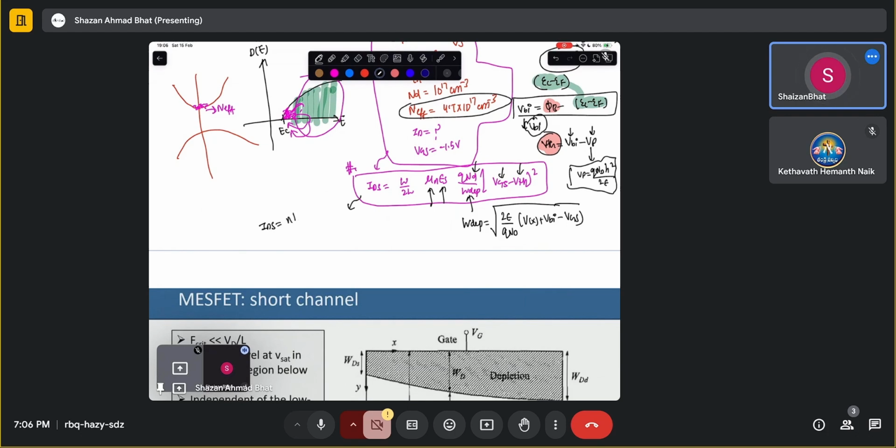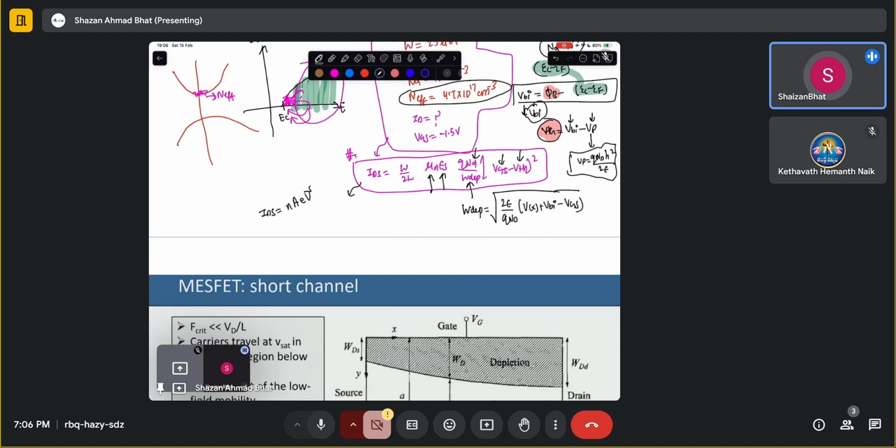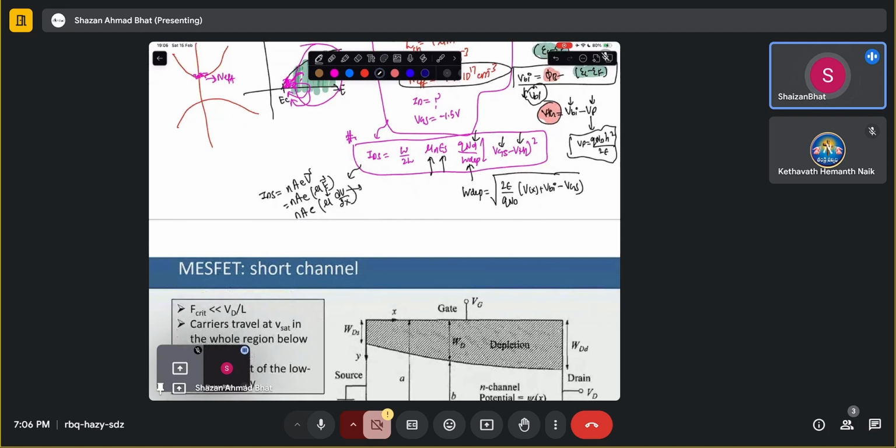It just comes from the fact that you know about this particular thing. If you know about the n q v_d thing, you can write it as mobility times electric field. You can just juggle with the things. Then you can write electric field as dV over dx, in terms of the voltage. Then you can replace it with the length. And then you have the area, you have the number, you can replace it with N_D. Then you have the mobility also. So these all come from these particular equations. You don't need to worry how these equations come up. They come from the basic electrostatic equations.